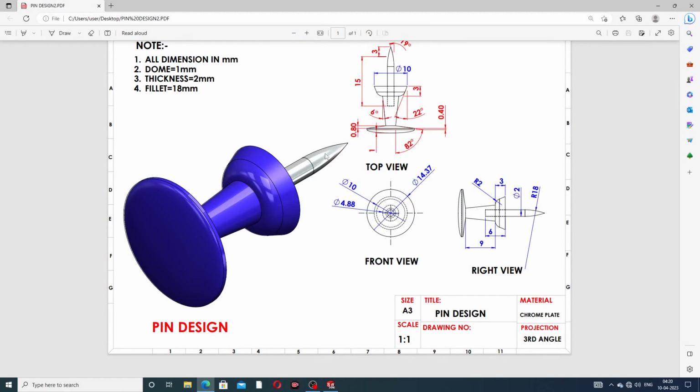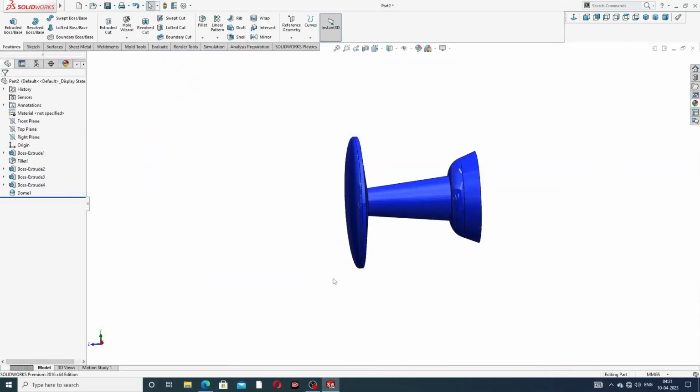And the next point is the pin drawing here, and some important points. This pin diameter is 2 millimeter, and at first drawing this inside is 6 millimeter and outward is 15 millimeter, and again 3 millimeter is 90 degree. Draft is available here.